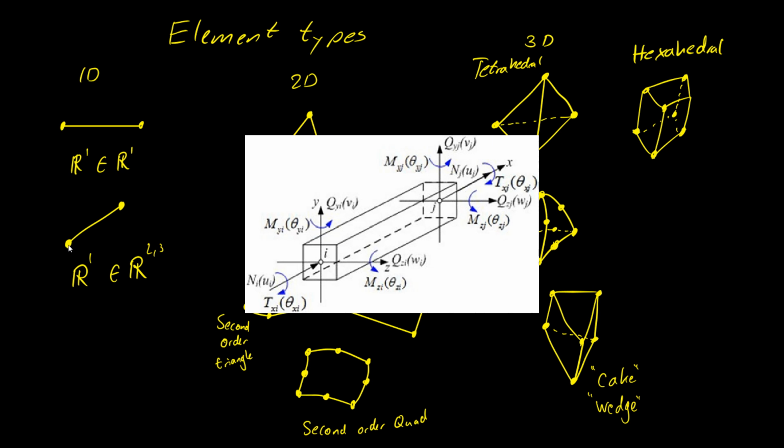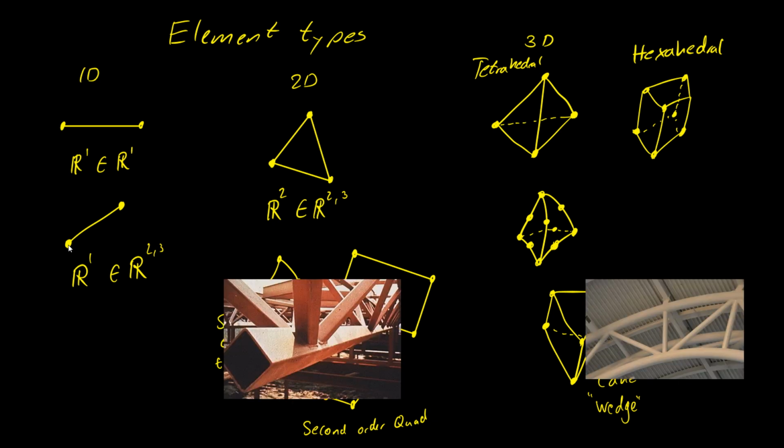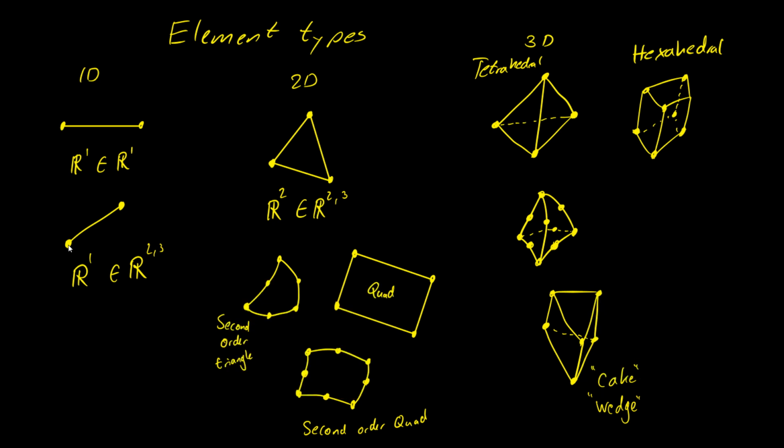But now we have beam constructions everywhere. We have beam designs everywhere. And if you're designing stuff out of beam truss works, they are defined by being welded. So at the connection points, they are typically welded, which means that when you're deforming such structures, if you're looking at an intersection point, then they are always going to have the same shape. So a beam element is usually deformed away from the connection point.